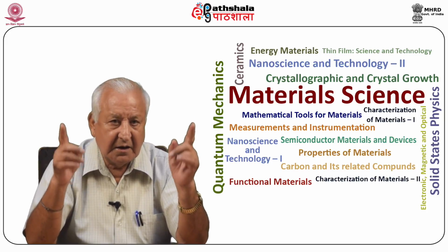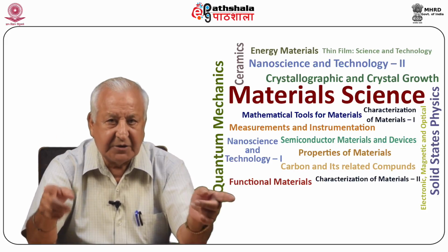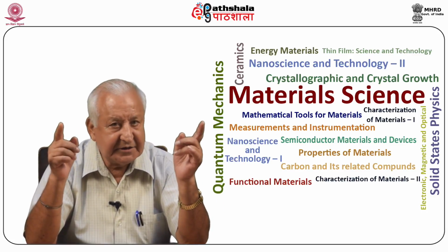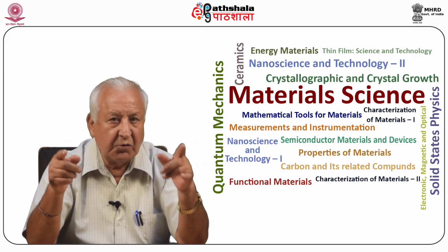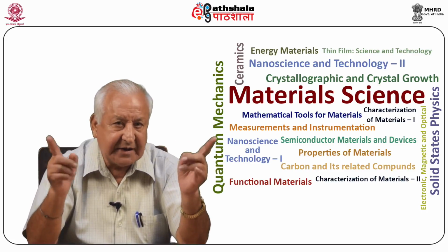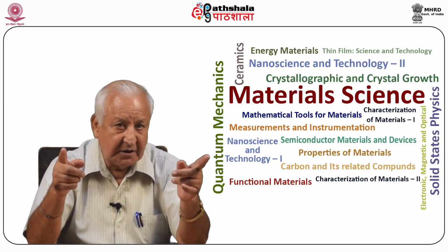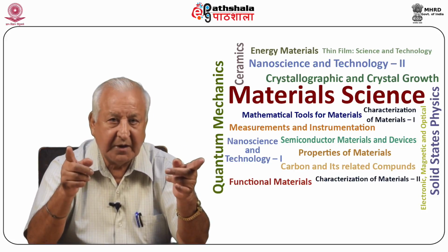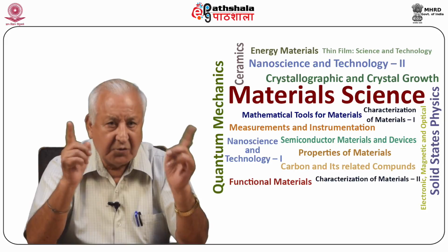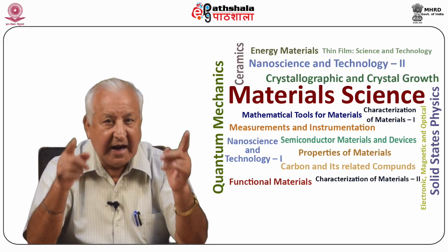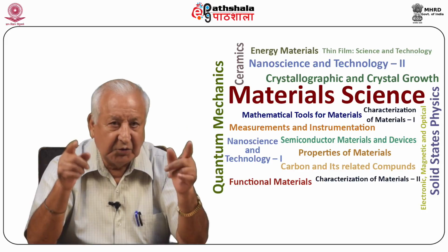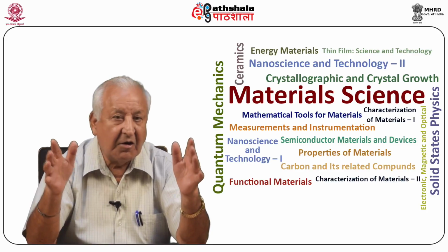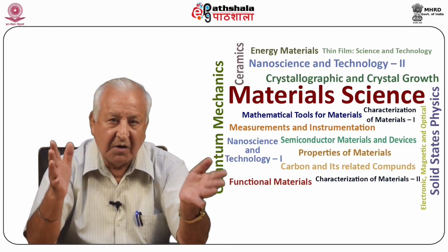In this regard, an important concept of dislocation density is introduced. It is defined as rho equal to S by V, where S stands for the total length of the dislocation lines and V is the volume of the crystal. It may be noted that rho has the dimensions of length raised to -2. So the quantity rho equal to S by V has the dimensions of inverse area and is called the density of dislocations.